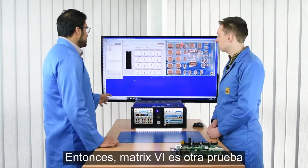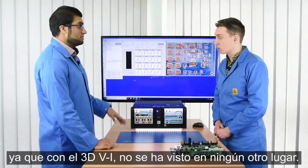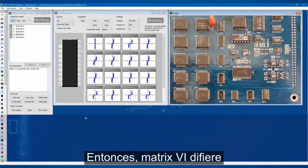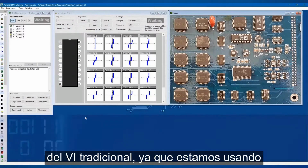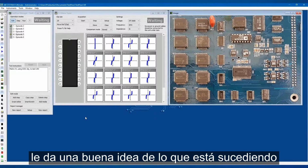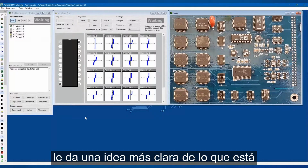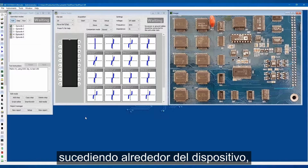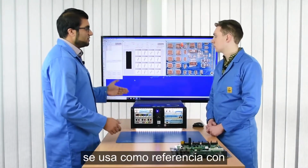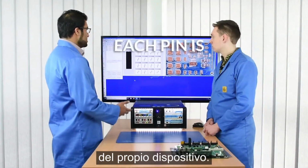So matrix VI, another exclusive test available with the BoardMaster, as with the 3D VI, very exclusive, not being seen anywhere else. The matrix VI differs from the traditional VI since we are using each pin as a reference. So this gives you a good idea of what is going on within the device itself. With the traditional VI, it gives you more of an idea of what is going on around the device, as we are using the ground as a reference. But since each pin is being used as a reference with the matrix VI, it gives you a good understanding of what is going on within the device itself.